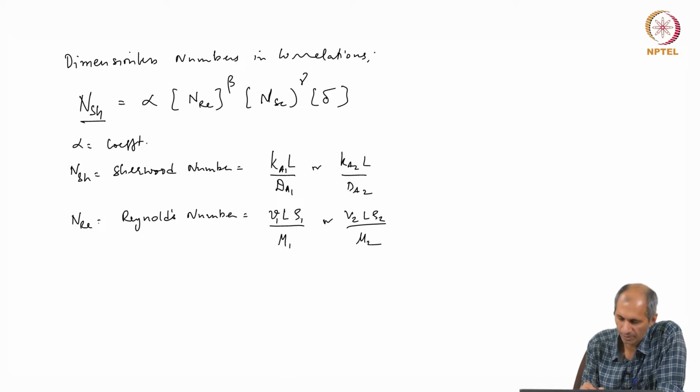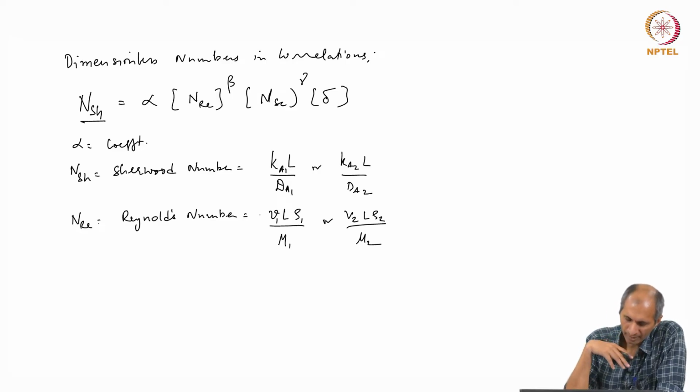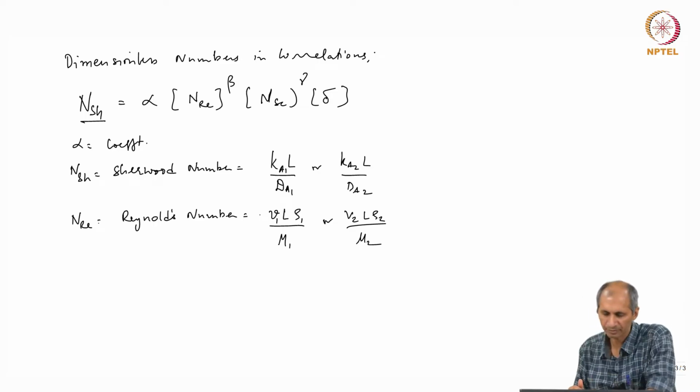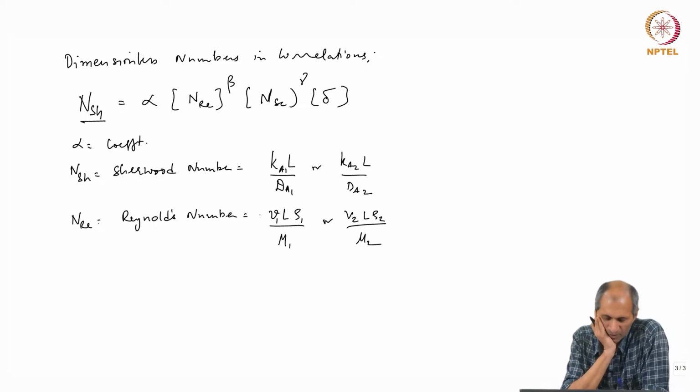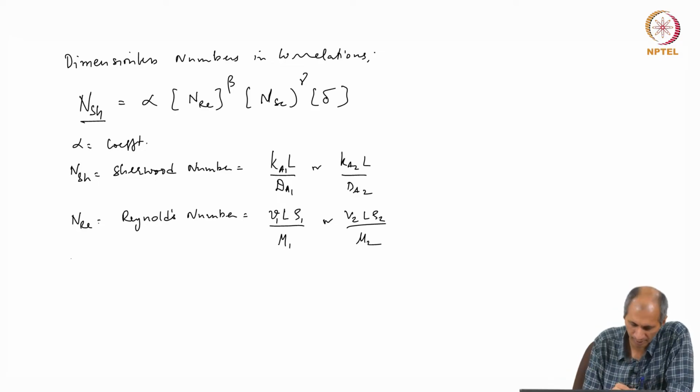This is the medium. So this is inertial force. Inertia, as we know, is a function of the velocity, and there is the density there, which is mass by volume. So inertial force divided by the viscous forces. The denominator is viscosity. So for the Reynolds number, if the velocity is high, the Reynolds number is usually high. That is the only thing that is changing dynamically in the system. So you can have something at higher Reynolds number.